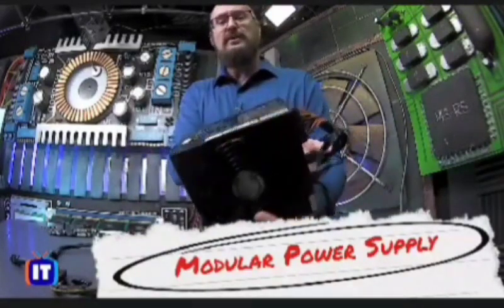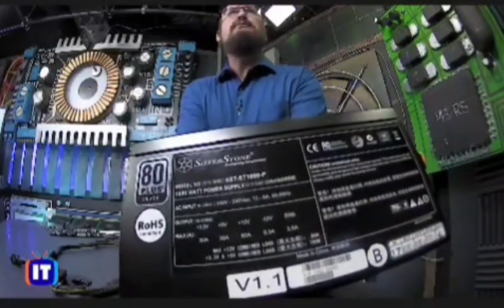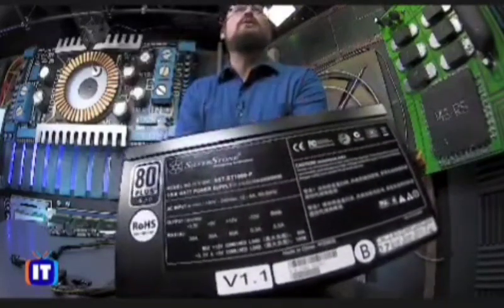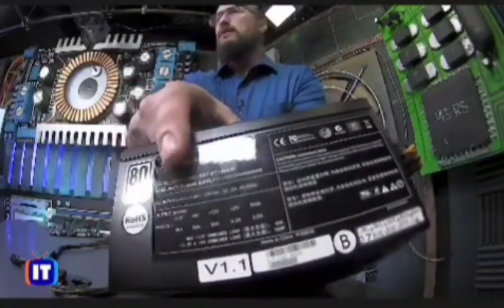And while we're here, let me go ahead and show you again the voltage ratings. Notice the output voltage, right? The output voltage lets us know that here we have that 3.3, the 5 volts down here, 12 volts as well. You also have a wattage rating as well. Notice that this is a kilowatt power supply.